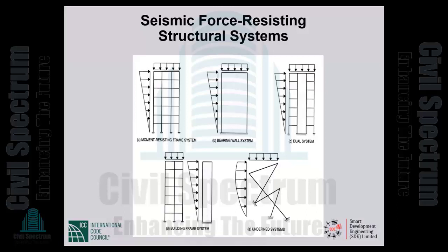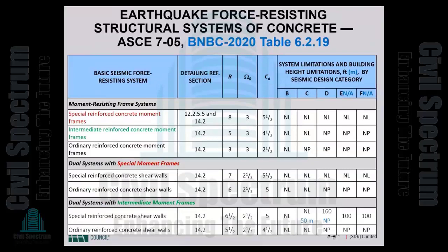Okay, this deformation compatibility requirement is an integral part of the definition of the building frame system. Everything else that we design falls under the category of undefined structural systems, which have to be designed by comparison with one of the defined systems. That's how the system works.